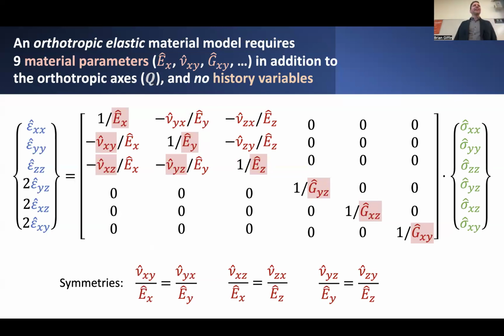It's a little bit more complicated, and it involves dependence on a few additional parameters beyond what we're previously familiar with. So rather than just Young's modulus and Poisson's ratio being the only parameters we have to come up with to characterize this behavior, now we have to come up with a total of 9 independent coefficients. You can come up with these coefficients by running a series of experiments that take some block of material and, in different directions, load it uniaxially in the X direction, the Y direction, and the Z direction, and you can come up with different values for the effective Young's modulus that would act in each of those 3 mutually orthogonal directions, which I'll call EX, EY, EZ.